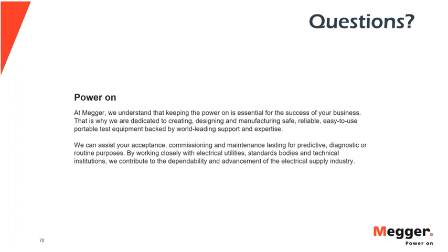DFR, dielectric frequency response, the very first application actually was on XLPE cables, which is basically your medium voltage cable. It's a little bit of a different approach, the analysis, but there is a method for that. There's an analytical process that is being used, using this variable frequency power factor analysis.